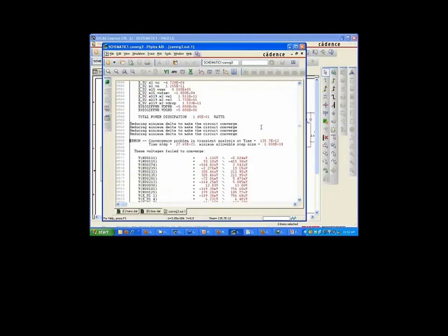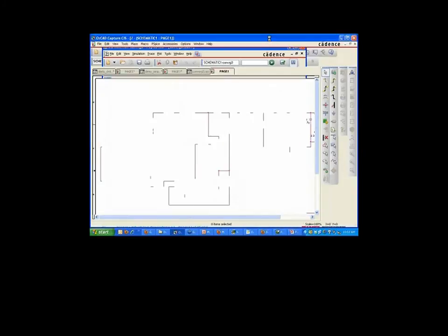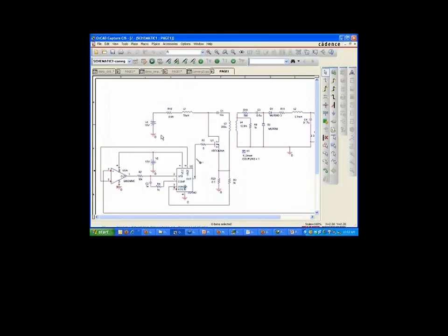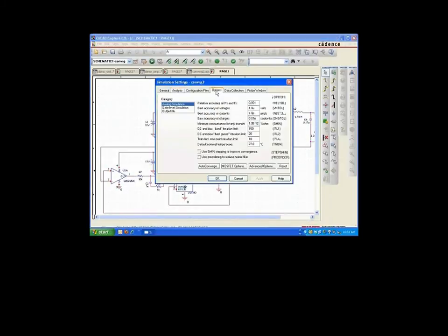So that's kind of frustrating. At this point, I have to figure out what's wrong with my circuit, why it's not converging, and that didn't really work out. So now I really have to break things down and dig into it quite a bit, maybe more than I'd want to. So what PSpice allows you to do now is you can just turn auto converge on.